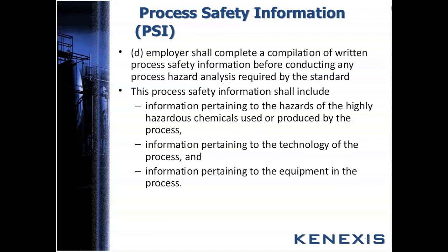And then information pertaining to the equipment in the process. What are we talking about here? Well, materials of construction, P&IDs, electrical classifications, ventilation system design, material and energy balances for the systems. What kind of safety systems are in place already? The relief system design and design basis. If you're going to give a relief valve credit as an independent protection layer in a LOPA, then you need to know whether the design basis of the relief valve is really acceptable for it to be an IPL. Okay? A topic of another subject later on.